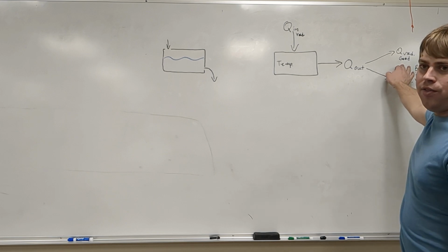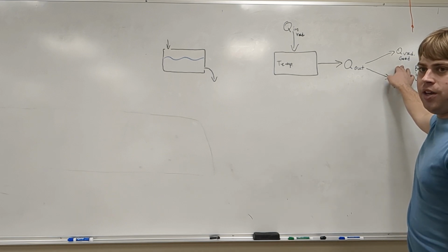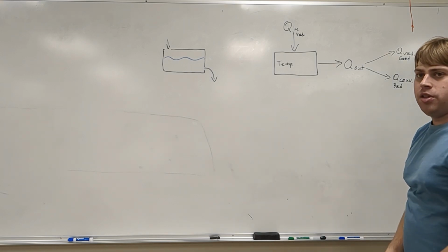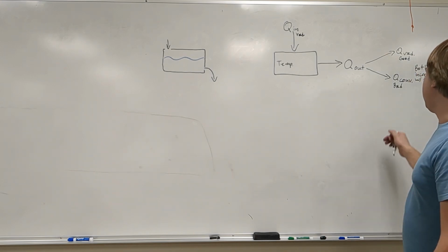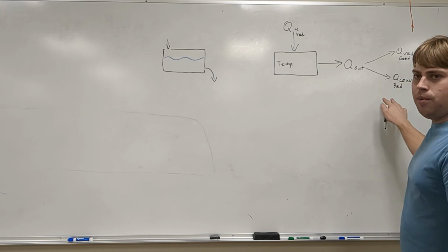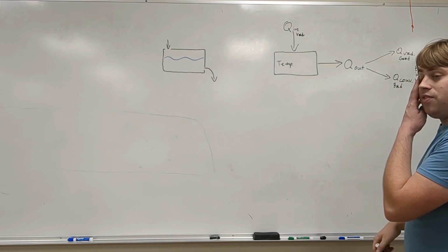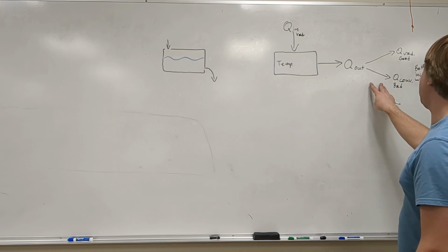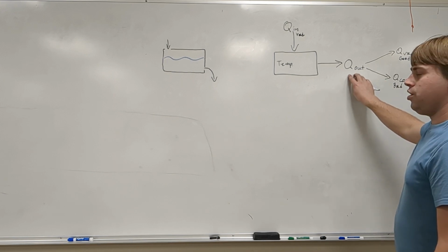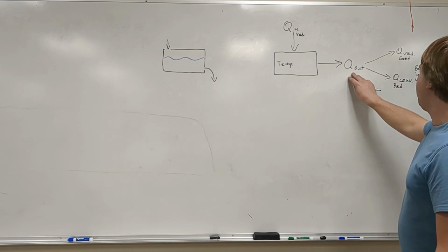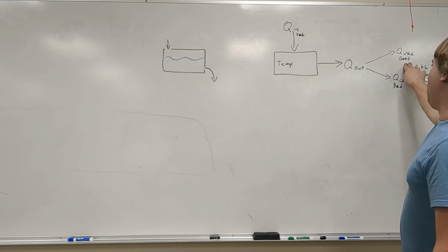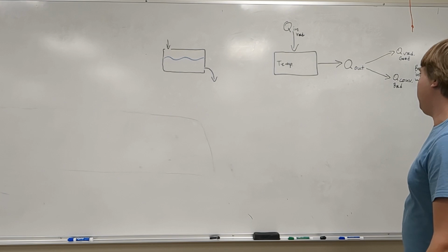But how do we quantify whether we have more radiation? Because both models have about the same geometry, we can assume the convection heat transfer is about the same for both. So if there is a change in the energy leaving the concrete, it must be attributed to radiation.